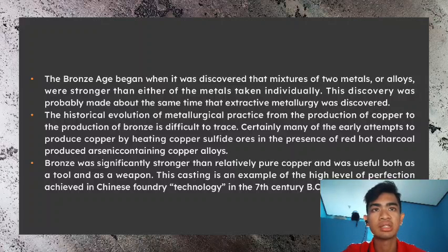Sterling discovered that the strength of silver could be improved greatly by the addition of a small amount of copper. The small addition of approximately 7.5% does not affect the appearance but significantly improves the serviceability of silver vessels, jewelry, and utensils.